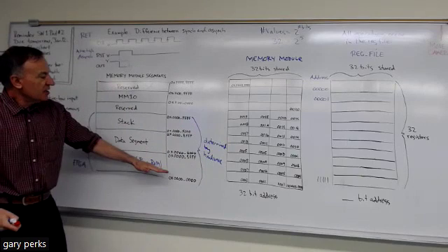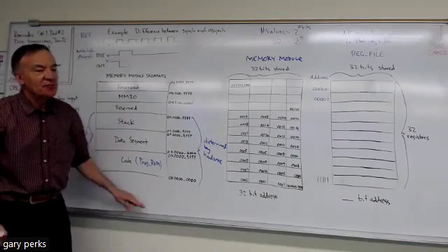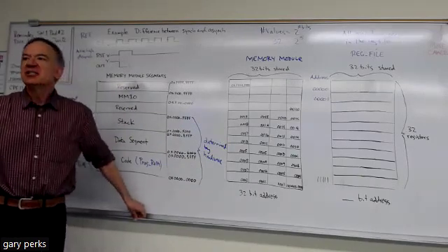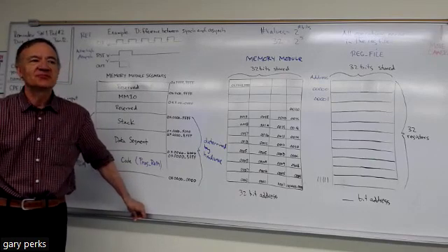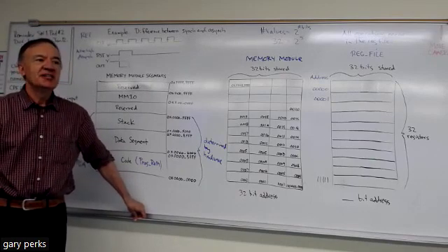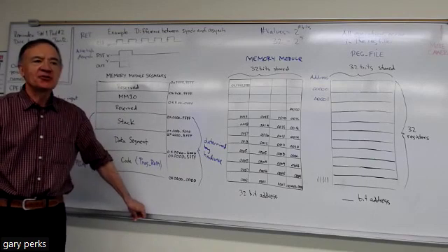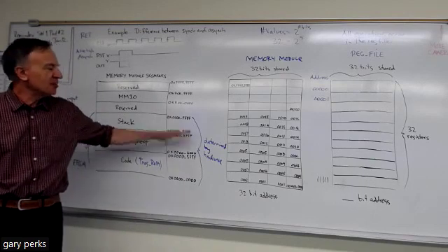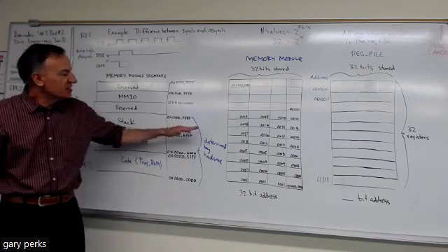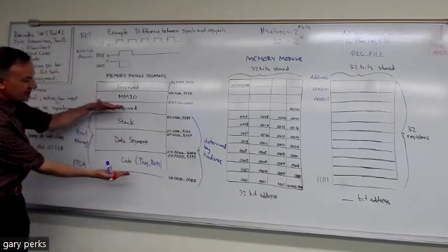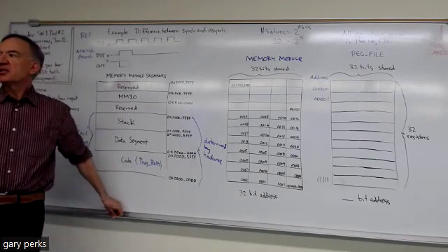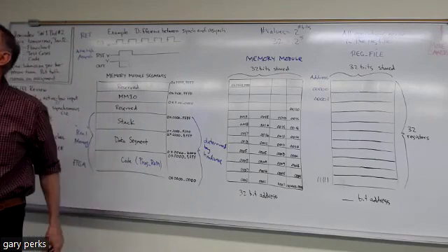We couldn't make real memory bigger unless we get a different FPGA, a different development board. If we use an Intel board or some other manufacturer, it might be different. But this is a limitation of the Basys 3 board. That's all the memory that we can fit in the FPGA.